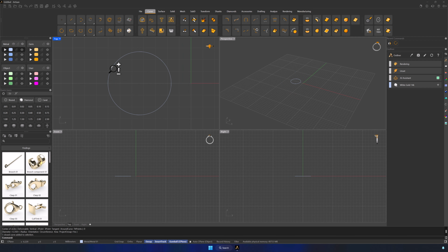Now, we'll create a vertical line at the center of the circle. Make sure OSNAP is active to select the center points. Now go to the top and click on the Trim command. Select the circle, then the line, and press Enter. After that, click on the right side of the circle to trim it. Now we can delete the created line.